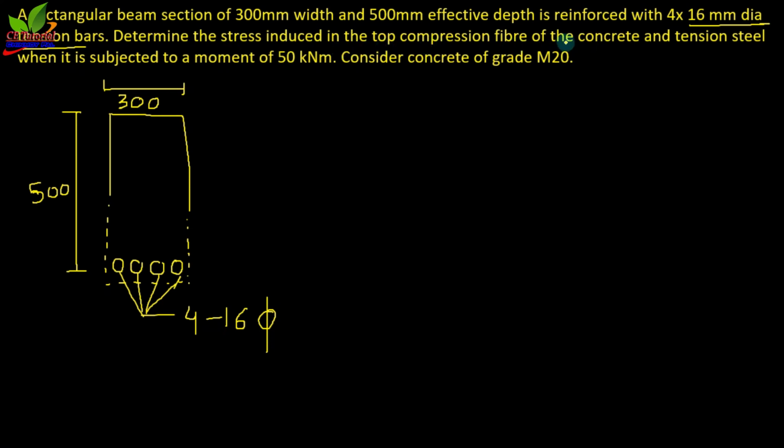Determine the stress induced in the top compression fiber of the concrete and in the tension steel when it is subjected to a moment of 50 kN·m. Consider concrete grade M20.